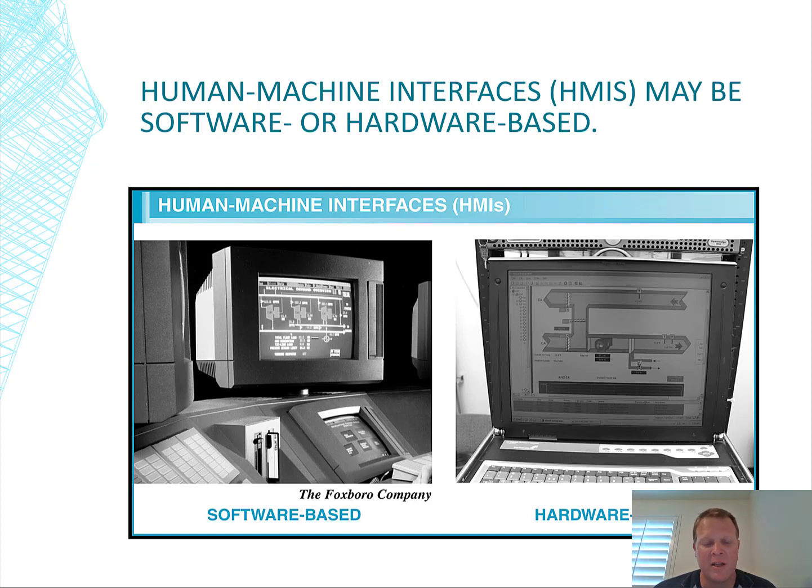I would pull up the HMI and log in. I knew what the password was and be communicating back to the controls contractor back in Salt Lake what I was seeing, and he'd have me force a few things on or force a few things closed, and let's see if we can get this equipment to run until he can get back out there, so we don't freeze any pipes or anything like that. We're trying to get an air handler running, and so it's pretty cool to be able to see this.